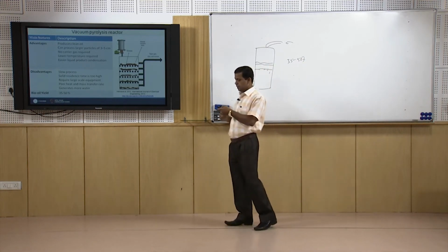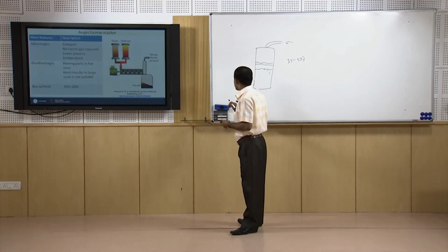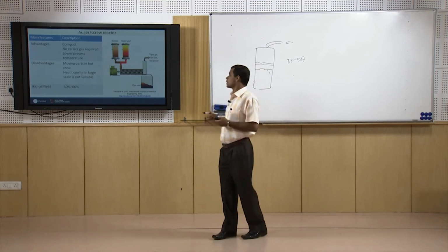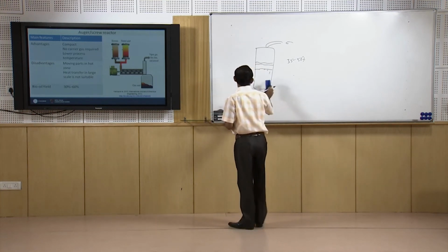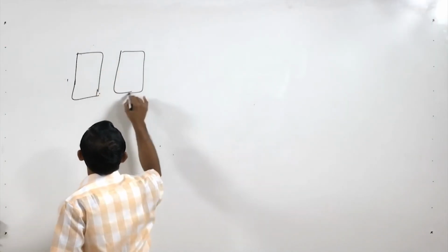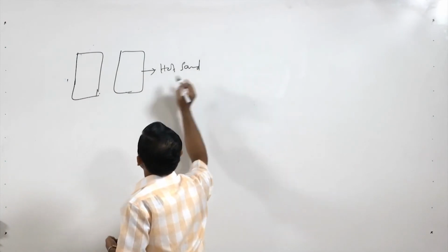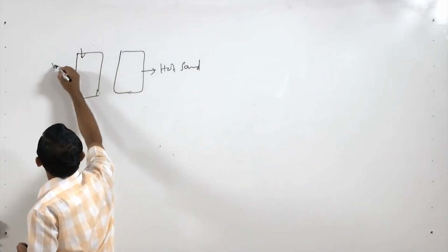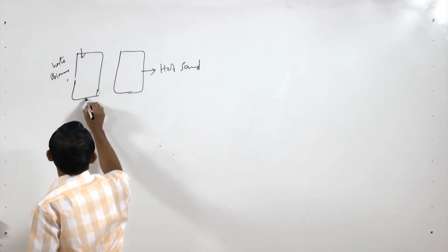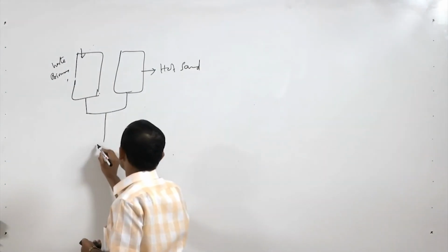That is why this is also not very widely used. Next, another development on this pyrolysis reactor is the auger or screw type reactor. In a screw reactor we use two tanks, one containing hot sand and another containing waste or biomass. So, these two are mixed. After mixing it goes to a screw.